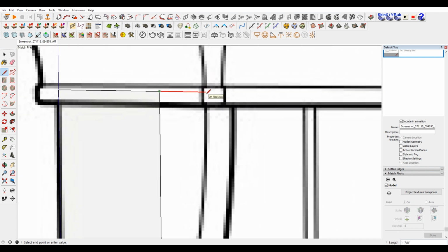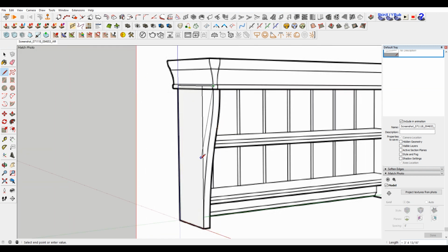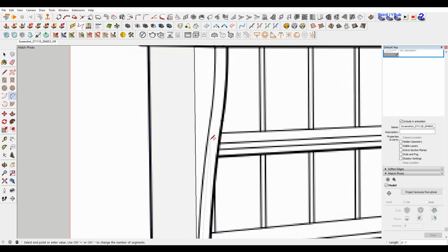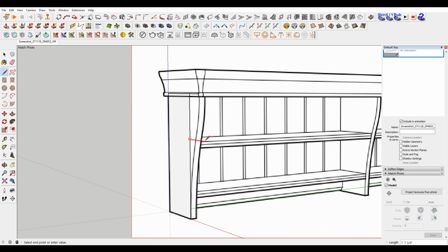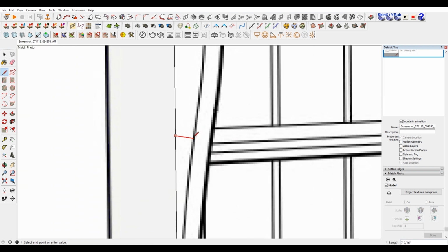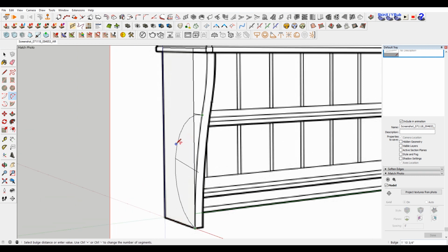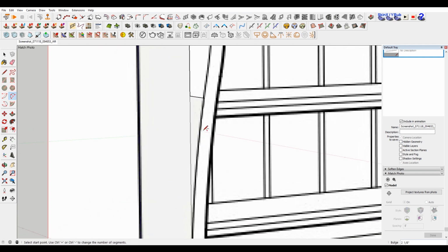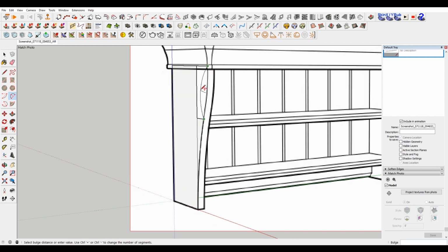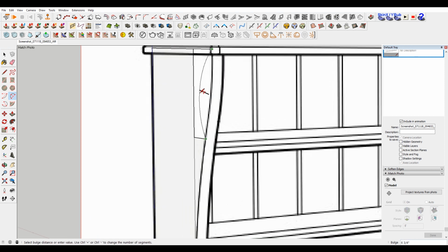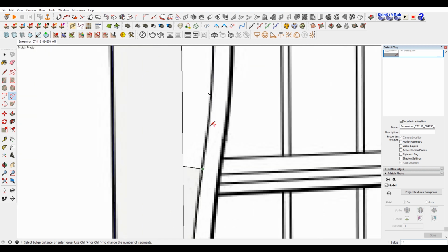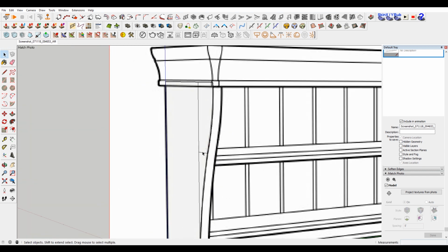one of the tricks here is that this is going to be a swoopy line, so there's essentially two curves here. So I would choose, let's say this is the tangent, so I'm going to draw a line here first. Let's say this is the tangent point between those. That way I'm making sure that I'm in the correct plane when I do this. So we have one here, and then another one here. Just select on this face, and then just holding shift, and I get a nice flowy line.